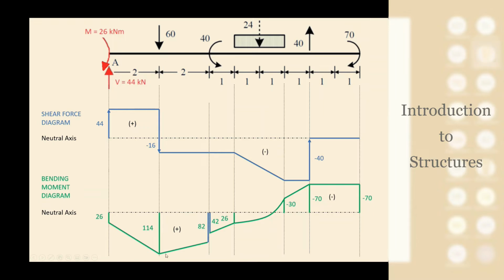Same thing in this interval and in this interval, and these two should be parallel because the slope is the same value. But it's enough to recognize that a linear function derived will give you a constant shear force: a linear function for moment, a constant function for the shear force. In the interval where you have a parabolic distribution of moments, you will have a linear distribution of shear forces.